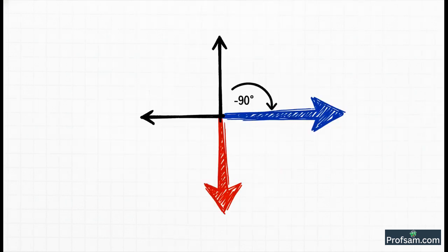So how do we use phasors to solve this? Step 1 is to draw a frozen picture of the situation at time t equals 0. For V1, the angle is omega t, so at t equals 0, the angle is 0. Its phasor is just a horizontal arrow of length 100. Easy. For V2, the angle is omega t minus 90 degrees. At t equals 0, that angle is minus 90 degrees. So its phasor is a vertical arrow pointing downwards, also of length 100. See what we did? We've turned those complex, wavy things into two simple little arrows.